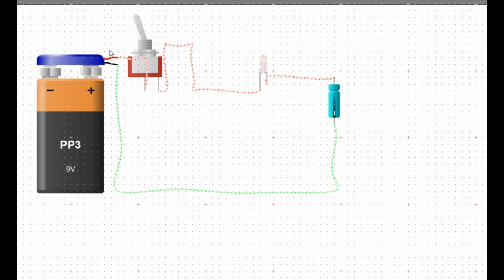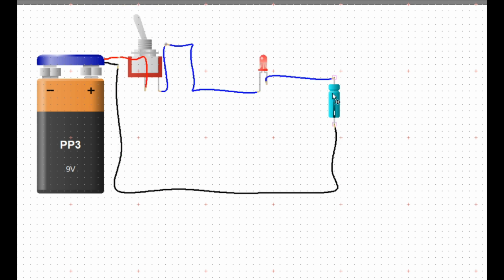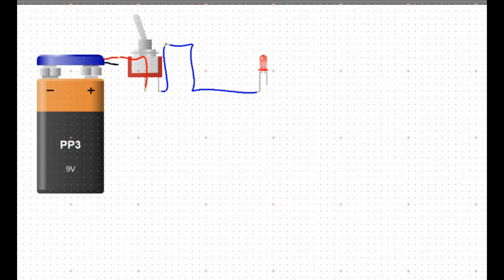Chapter 4. Key differences between inductors and capacitors. The behavior of the two circuits highlights the key differences between inductors and capacitors. 1. Inductors. Allow DC current to flow once the current stabilizes. Resist changes in current. Act like a short circuit in steady-state DC circuits. 2. Capacitors. Block DC current once fully charged. Resist changes in voltage. Act like an open circuit in steady-state DC circuits. These differences explain why the LED glows with the inductor but not with the capacitor.